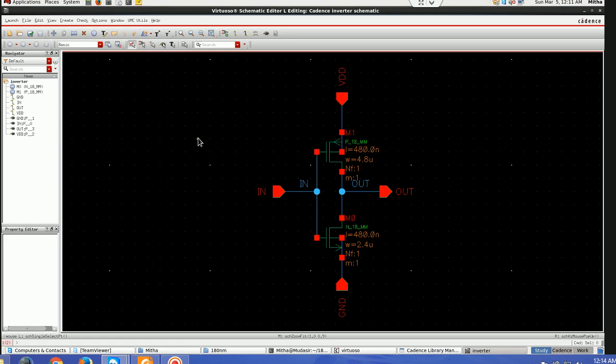This is tutorial 10 of Cadence Virtuoso IC615. In this tutorial, I'll be showing how to do the corner analysis of our design. Corner analysis is used to find the process inaccuracies, temperature, and other process and parameter variations. In this simulation, we see the effect of process and environmental variations on our design.